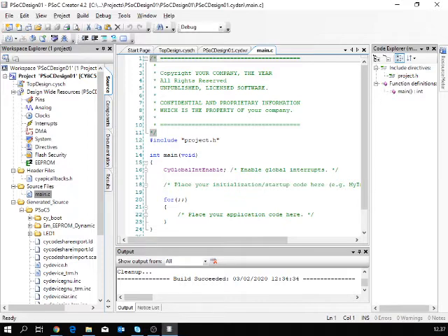Why it's called a function is because there is also the boot.asm, which is basically the boot code that first calls the initialization routines, which are system level routines, and then calls main.c. The main function should be never ending.